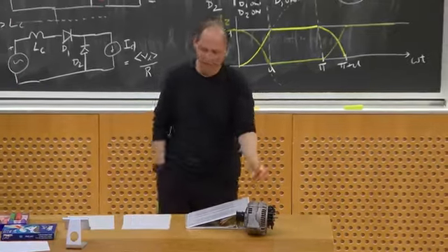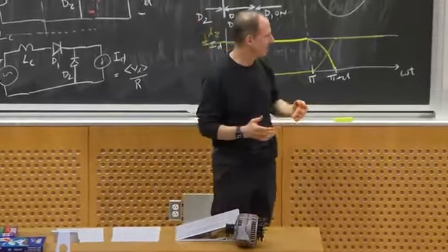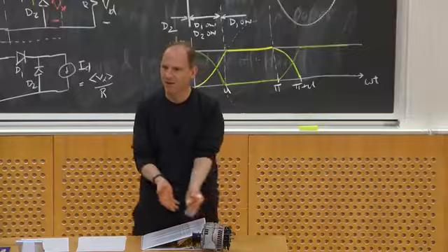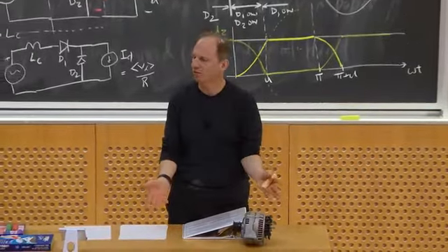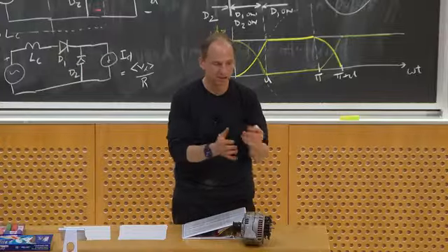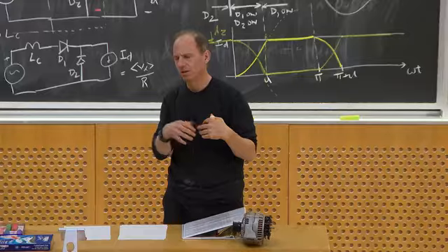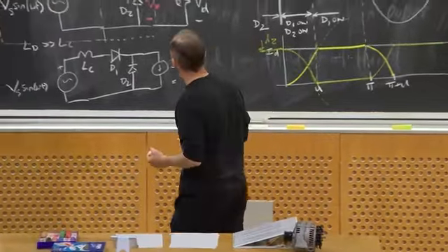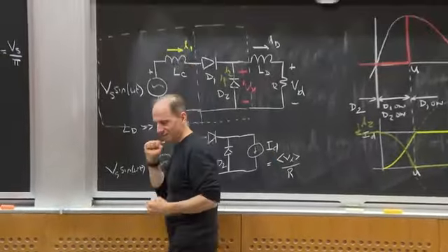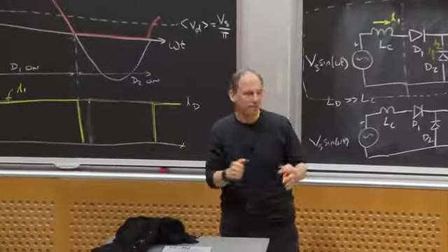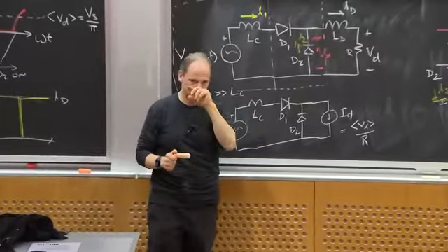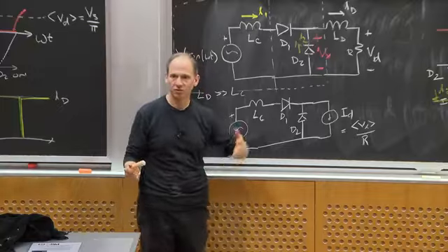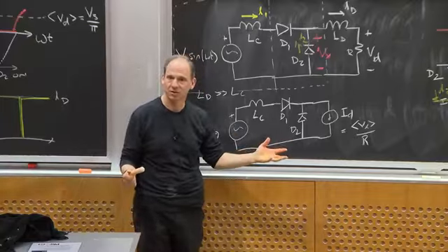So there's all kinds of examples, and like I said, I showed it to you in the simple half-wave rectifier. This isn't even that, this is a three-phase rectifier. The math for it's all about the same. It does the same kind of thing. You can also get this in other contexts where, instead of series inductance, shunt capacitance, such as owing to diode capacitance, can also mess with your ability to rectify voltage and get energy out of an AC system, all right?